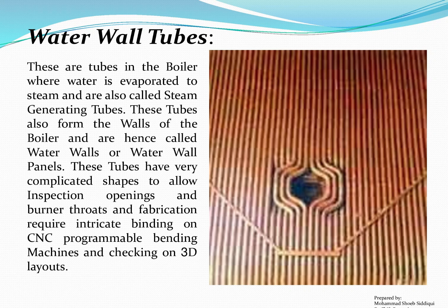These tubes also form the walls of the boiler and are hence called water walls or water wall panels. These tubes have very complicated shapes to allow inspection openings and burner throats, and fabrication requires intricate bending on CNC programmable bending machines and checking on 3D layouts.